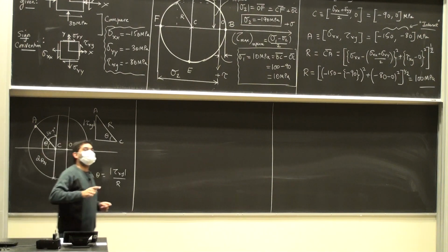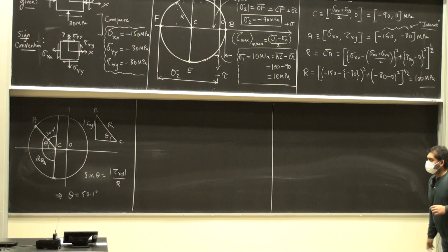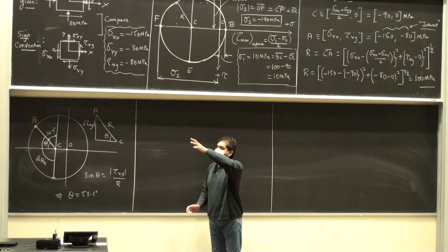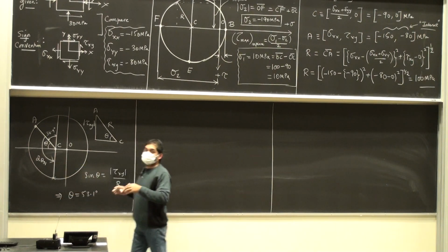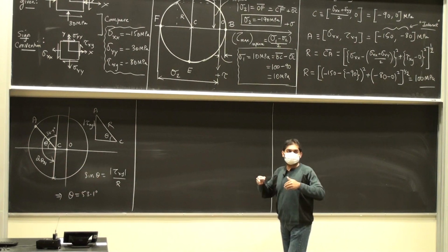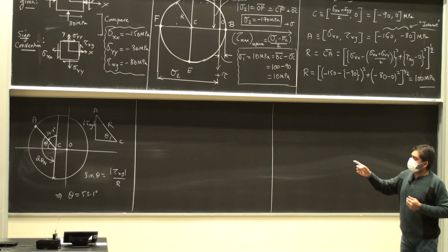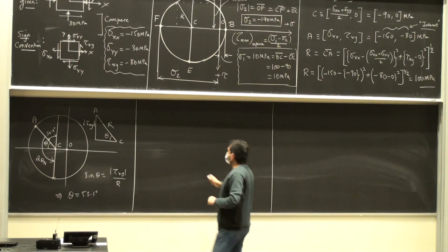And I'm going to use that value as well. Okay, so bear with me. So first time I'm going to go from CA counterclockwise to the first shear stress value that I reach. Okay, counterclockwise. 2 theta S1 is going to be whatever the theta is plus 90 degrees.